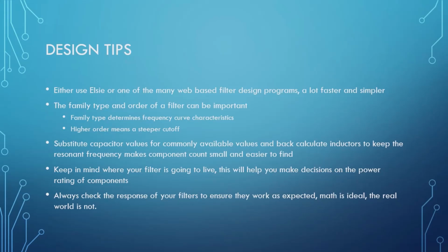And then actually, just as Roger was saying, once you get your calculation, you say, okay, I have this capacitor, right? Then go back and recalculate your inductors based off of that value you have for the resonant frequency using the equations we were looking at earlier before.